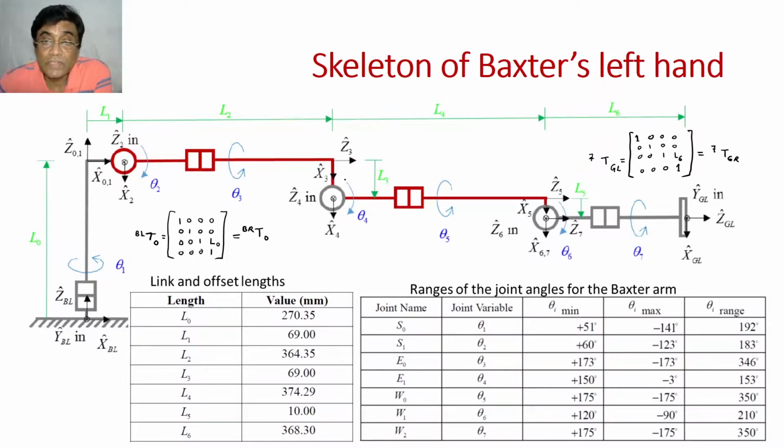You see here, one should notice that the theoreticians, who dislike the numerical methods, although nobody can really dislike them, because today this is the most practical solution of industrial robot problems. But even then, if somebody wants, you see, this is the skeleton of the left arm. So here is one joint, here is joint 3. Joint 4 is perpendicular to the plane of the whiteboard, this is theta 4, then theta 5 joint is there. So this is the axis of the theta 5 joint. And L5, the link length, if you compare with all the other L, is very, very small, isn't it? 10 millimeter.